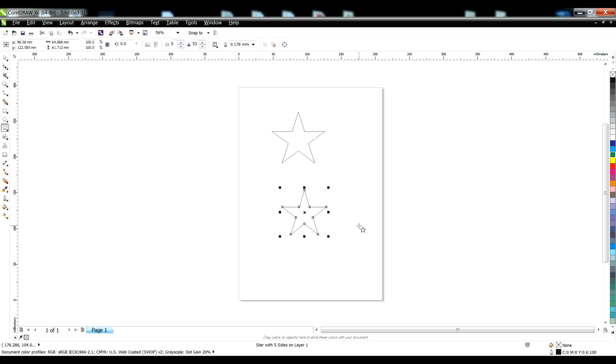And if we want to draw a star with equal sides but with our starting point being the center of the star, we hold the shift and the control key on the keyboard at the same time. We press and hold these two keys, click and hold our left mouse key and drag to a corner, the down right corner for example. Now we are drawing a star with equal sides, but the starting point is the center of the star. If we let go of our left mouse key, we have a star with equal sides with the center as its starting point.